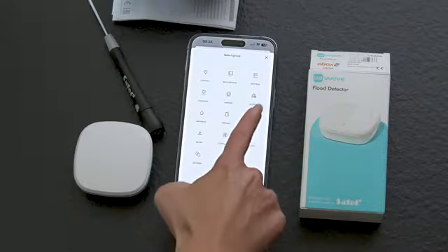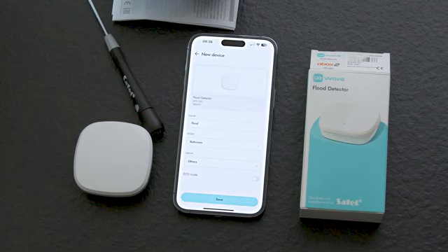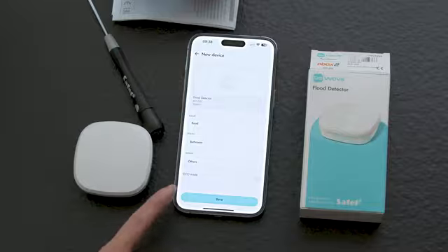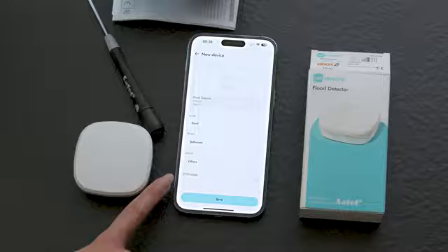Do you remember me saying that the Use for Protection mode is enabled by default for all devices with a few exceptions? The flood detector is such an exception. That's why you can see here that we only have one additional option at the end, the echo mode. Why is there no Use for Security option? Because in the case of a flood detector, we want it to be armed non-stop, not just in the protection mode. The same goes also for a smoke detector or gas detector, for example.